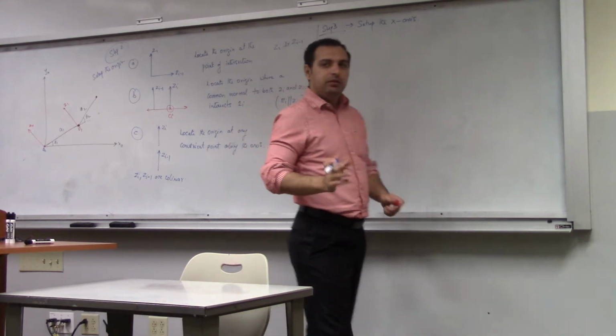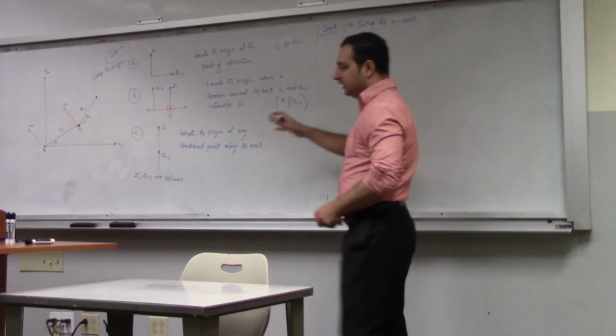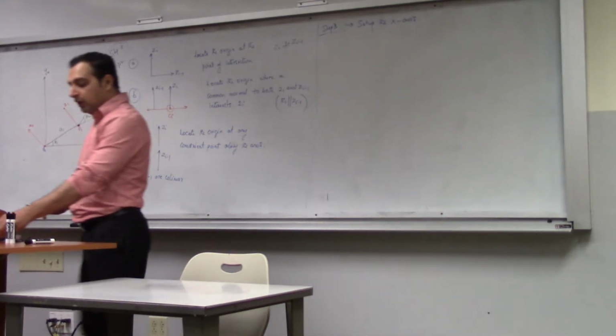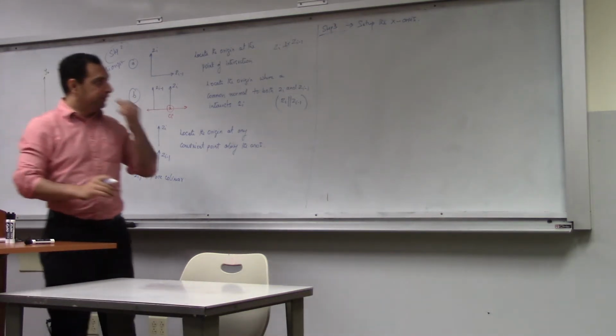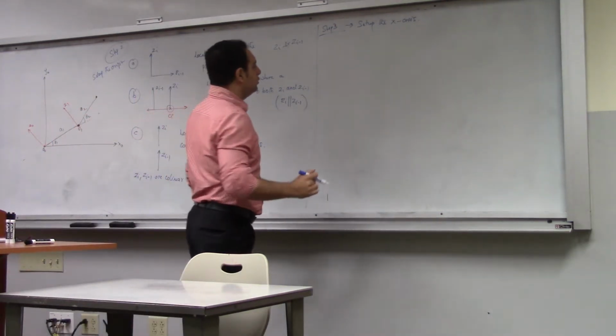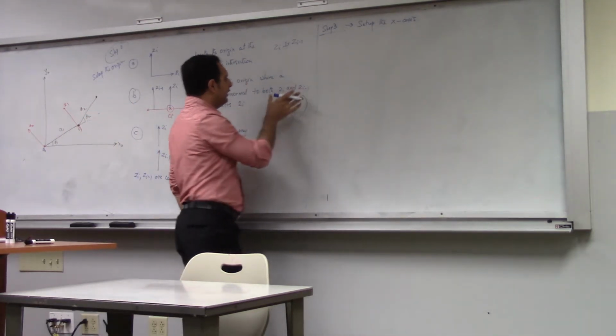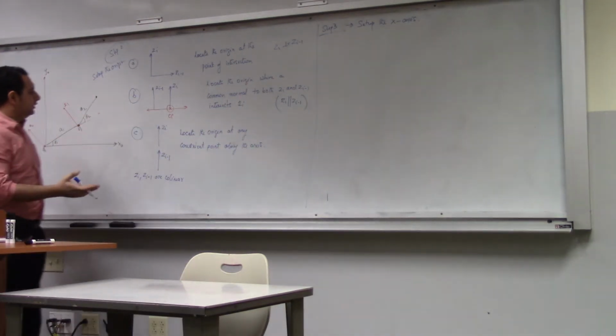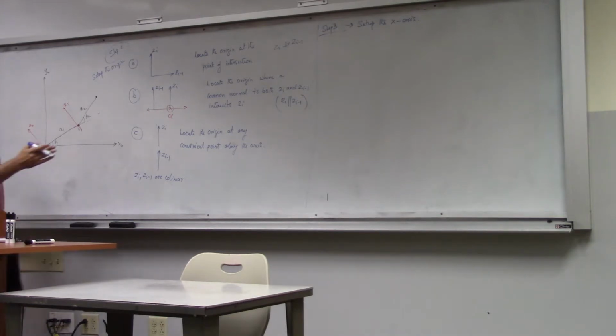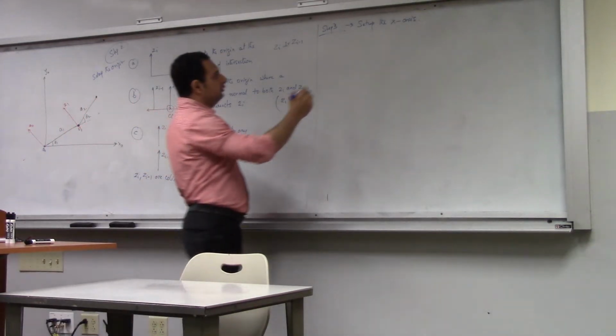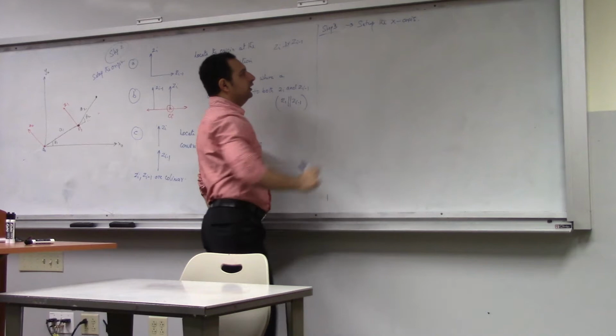The table might not be unique. For example, depending upon how you set up the axis, you might get a different table. But eventually, when you do the homogeneous transform, it has to be unique. Otherwise we'll end up with different transforms for the same structure, which will lead you to 2 points for a given joint displacement.